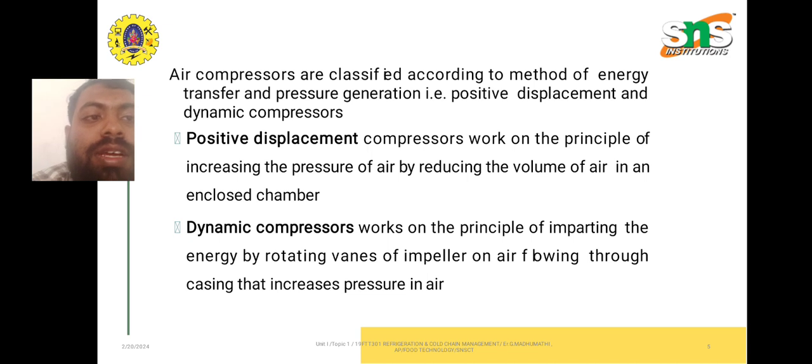We have seen that air compressors are classified according to the method of energy transfer and pressure generation, that is, positive displacement and dynamic compressors. Positive displacement compressors work on the principle of increasing the pressure of air by reducing its volume in an enclosed chamber. Dynamic compressors work on the principle of imparting energy by the rotating vanes of an impeller on air flowing through the casing, which increases the pressure of the air.